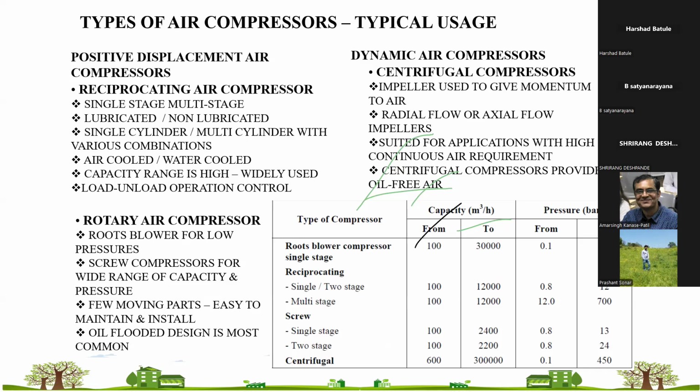So considering my requirement is 6 bar at the equipment terminal, I'll select the compressor considering the pressure drops across your circuits. Then there will be a pressure drop across your filters. Then dryers will have some pressure drop. There will be another pressure drop if we are having leakages in our line, so considering a safety margin, we'll be selecting 7 bar.